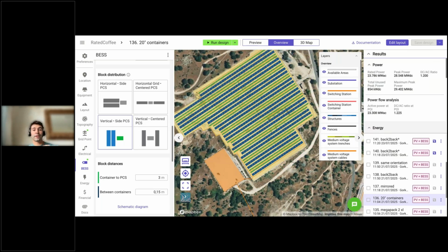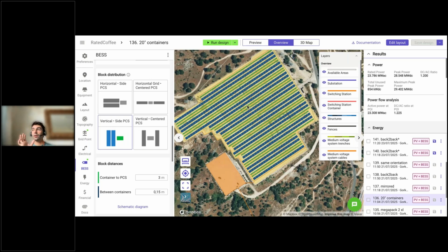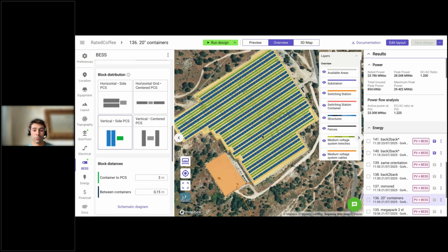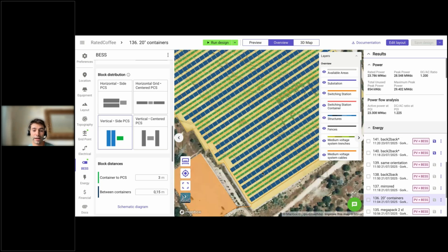If the battery area starts being a bit more weird with more edges and so on, the rotation angle may not look perfect. We always try to install as much capacity as possible, so we try different angles, but if the battery area starts getting very complicated, the task for the algorithm also gets more complex. So maybe you can play around with this rotation angle and try to find the most optimal angle, but in most cases, it will nail the configuration like in this case.